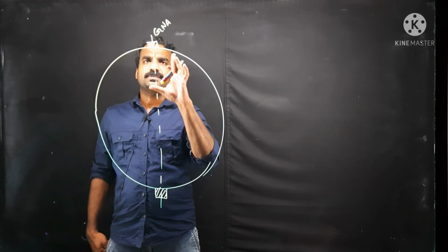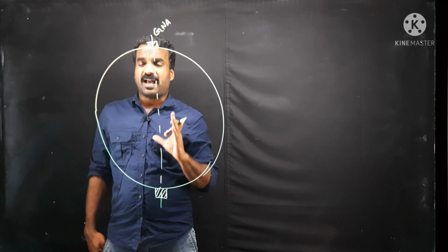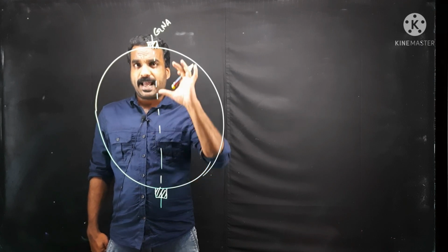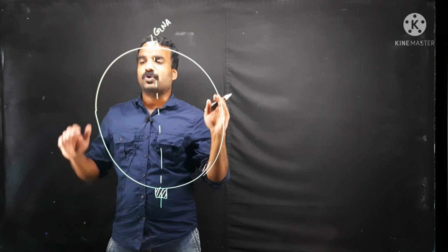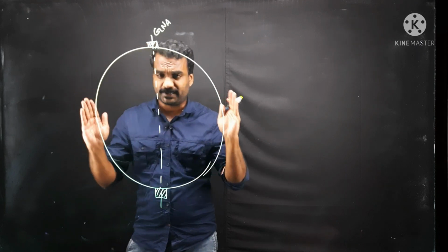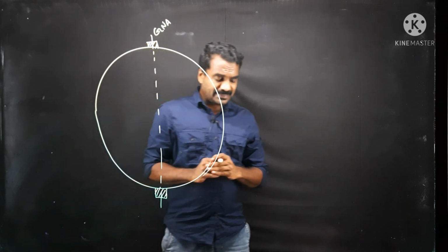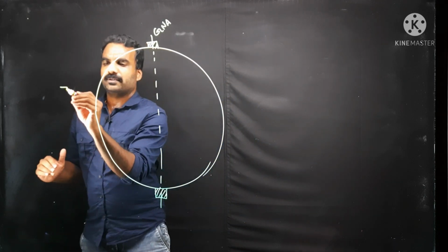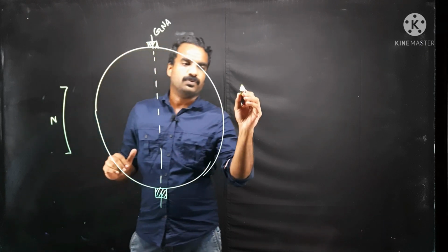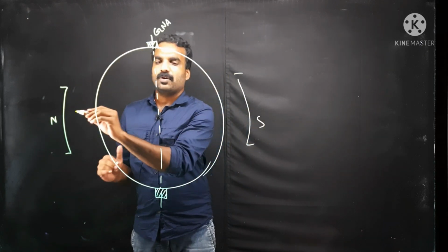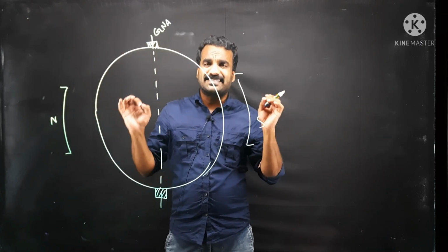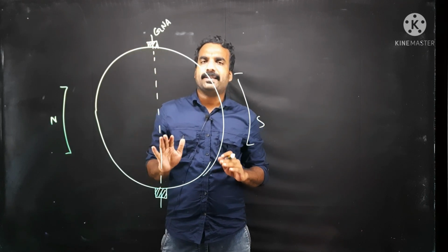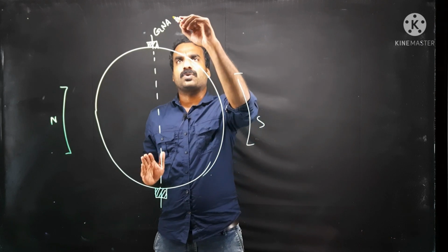This is the ideal position of the brush, but it is correct only when there is only the main pole present. If the flux in the system is just main flux passing from north to south, GNA and MNA are aligned on the same point.